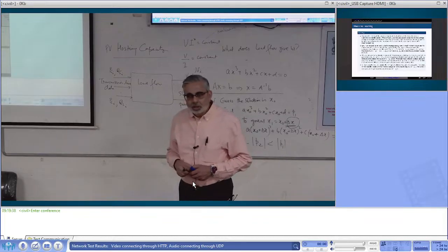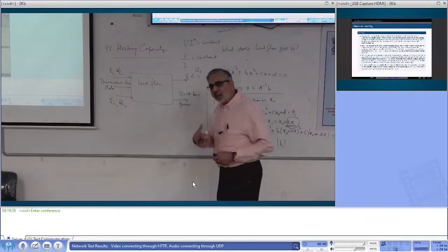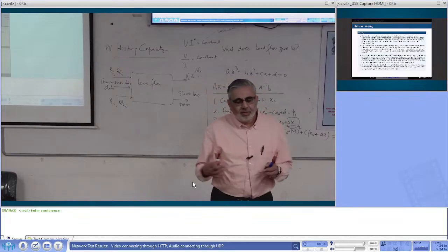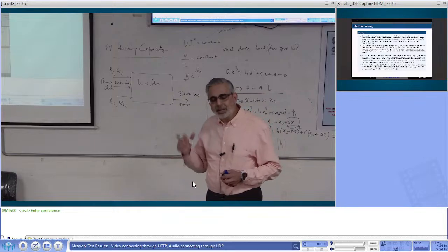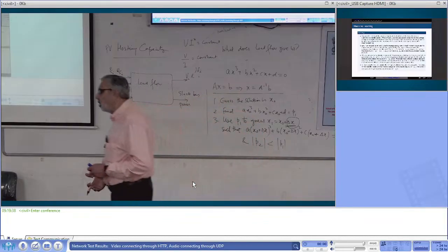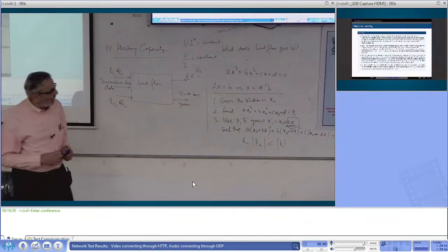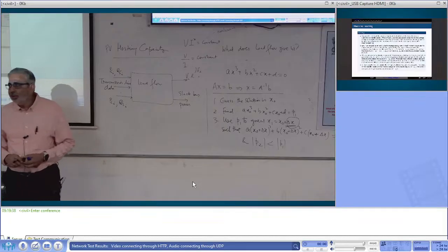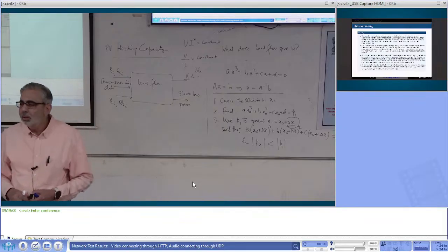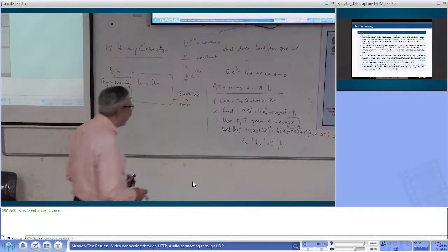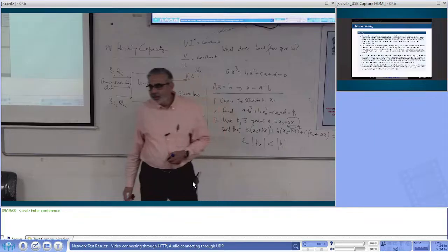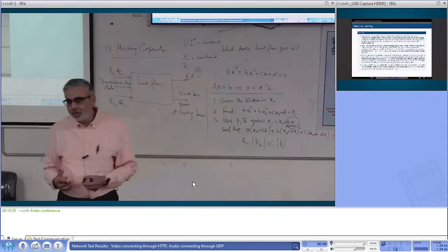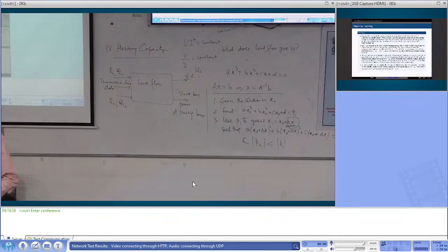So this is how many slack buses there are in the system and all that. This is all very interesting because many times the solution depends on that, and many times it's a regulatory requirement, etc. But remember there is a slack bus. Maybe there is another name, I'm forgetting. Swing bus. It is called slack bus or swing bus because it is not fixed power. It will depend on how the whole thing works out.